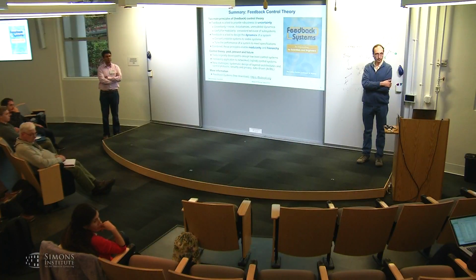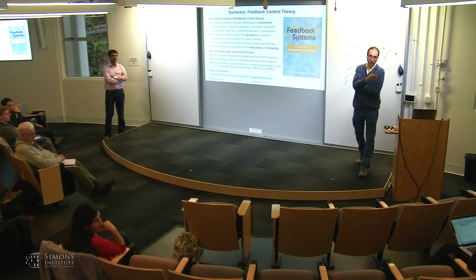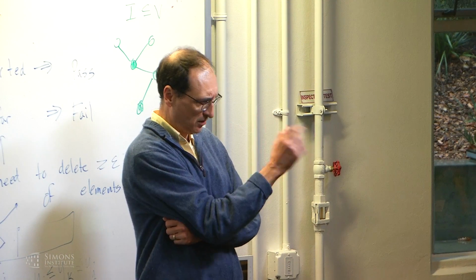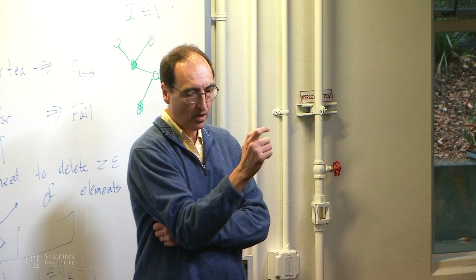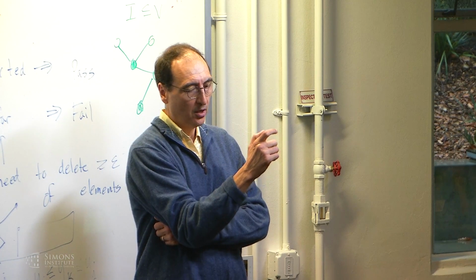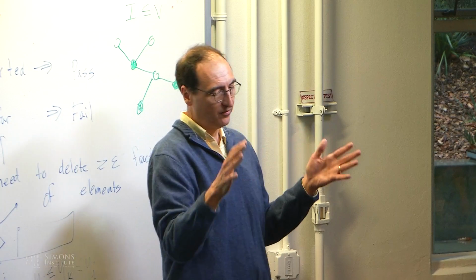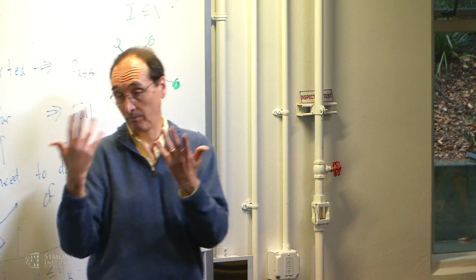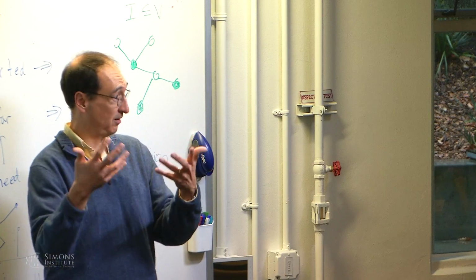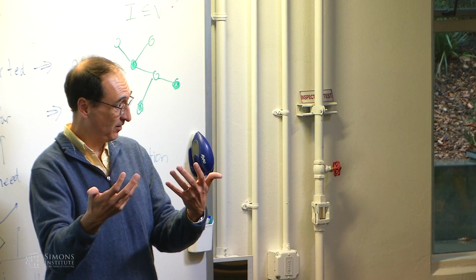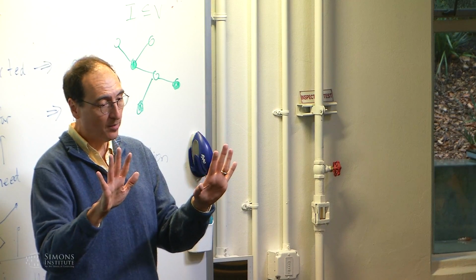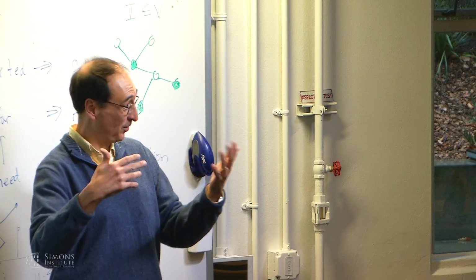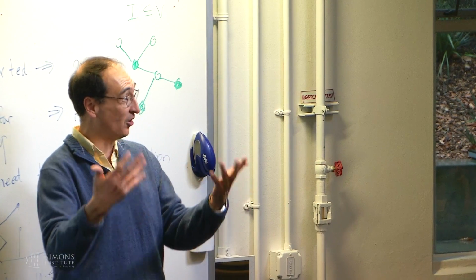I mean, there are some security considerations as well. Yeah, so the other one you would worry about, and just say the aircraft control industry worries about this a lot. Not so much because of adversarial stuff, but typically in an aircraft, depending on how safety critical it is, you have 2 or 3 processors doing your flight controls. And they'll vote, they typically use a Byzantine consensus algorithm to make sure that if a controller fails, the right thing happens. But the other thing they worry about is common mode failure, right? So there's a bug and it's the same algorithm running on each one, and so the same bug, they all interpret the signal differently.